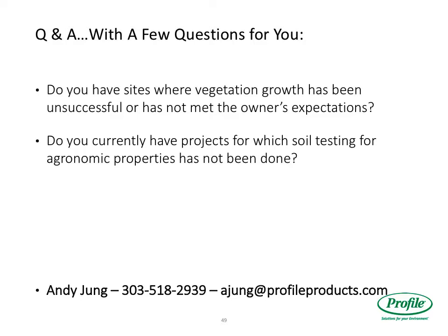On stockpiling soil to store the organic matter in the soil, is there a protocol for stockpiling soil to preserve that, or is it always going to happen? Can you repeat the question? The question was, when you stockpile your soil, how can you prevent the loss of the biological activity? I was reading one paper where they referenced you could till it periodically. That's probably not as effective either. It's basically a function of depth. With a 30-foot pile, after about 2 feet, 5 feet, 10 feet, everything below 10 feet is going to be dead. So you could have a thinner lift, and that would work better to maintain that biological activity. The organic matter should still remain, but you're just losing the biological activity.